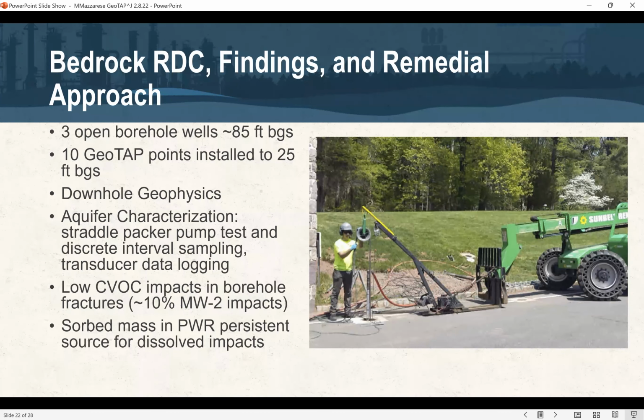And so that's primarily there. We're just using water to isolate the fractures that are identified by the geophysics, and using a set of transducers to be able to see what the overall distribution and the fracture network looks like by monitoring the adjacent monitoring wells.